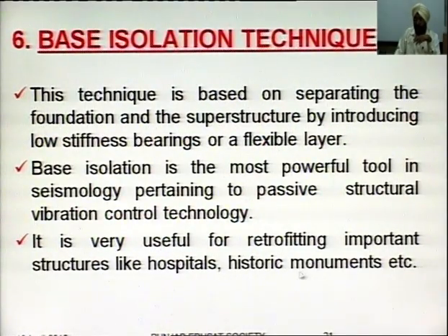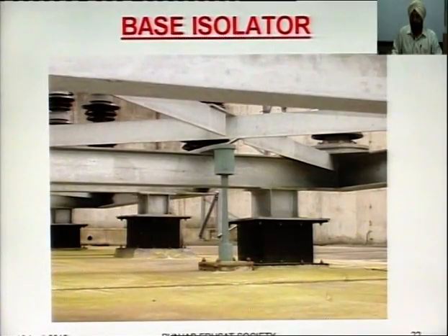So all the historical monuments which are very precious for us, the hospitals, the commercial buildings, the public buildings, are provided with this base isolation technique to keep them safe against earthquakes. Look at the diagram, you will get a clearer idea. This is the natural ground level and the foundation part is already casted here. This is showing the base isolator. These black colored bearings are showing a foundation of a very heavy structure, some electrical fitting it looks like, and this superstructure part is isolated from the foundation part by providing these base isolators.